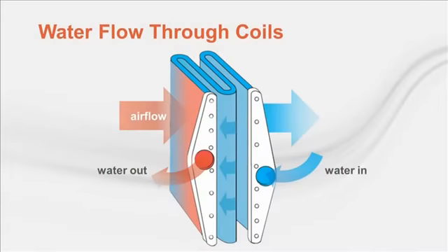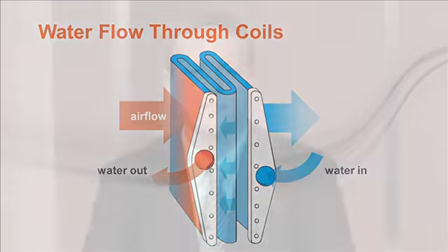The velocity of water through the coil tubes is determined by the geometry of the coil. Contributing attributes include the tube diameter and how the coil is circuited. By varying the number of tubes fed and the cross-sectional area of these tubes, a variety of flow patterns can result. Let's look at some different ways to circuit a water coil.